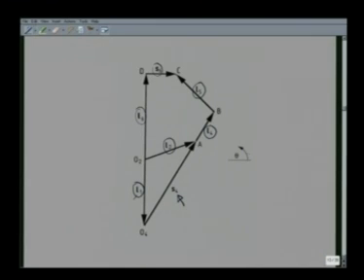And the orientation of all these vectors I represent by angle theta measured from this horizontal line in the anti-clockwise direction. So we can have one closed loop O2A O4 O2, which means L2 is equal to L1 plus S4. This is one loop closure equation in terms of link length vector and sliding displacement vector.